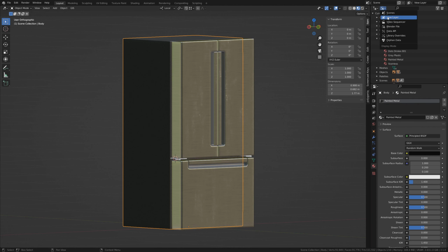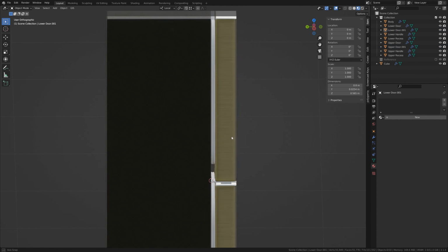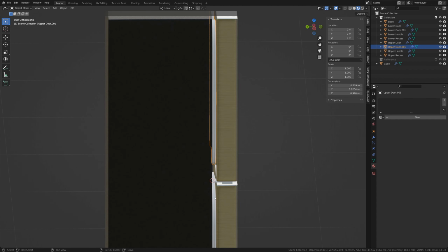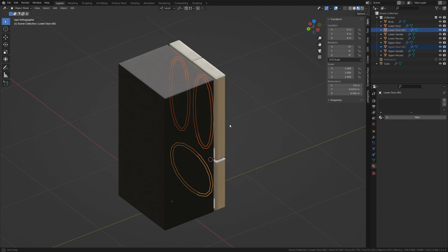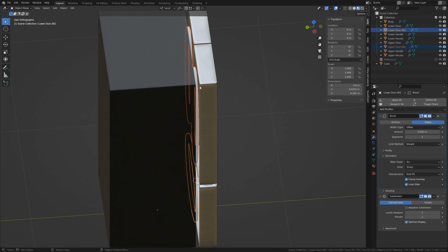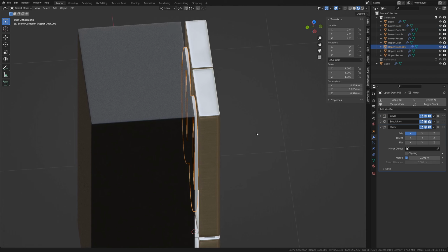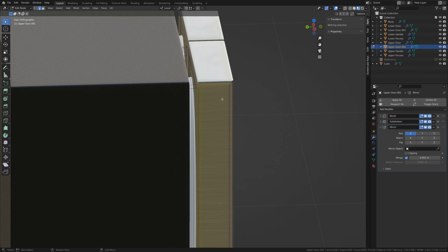Going back to View Layer, one thing that I have still not done that I noted before was to put the bevel modifier on these seal objects. Or rather, it has a bevel modifier, but we need to mark the bevel edges. So let's select one of these seals because what we're about to do does not work when editing two objects at a time. Go into Edit Mode, select all edges, and change them all to a bevel weight of 1.